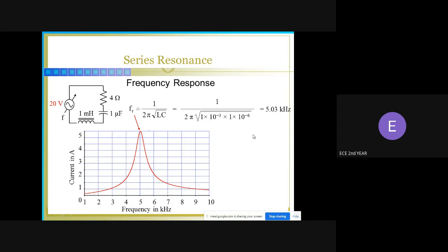At this time the circuit impedance is equal to R. So in this resonance frequency condition, the circuit has only the resistance value. This is a very low resistance in this condition, so the maximum current will flow in this circuit. I equal to maximum in this condition, because XL is equal to XC, so both values get cancelled.